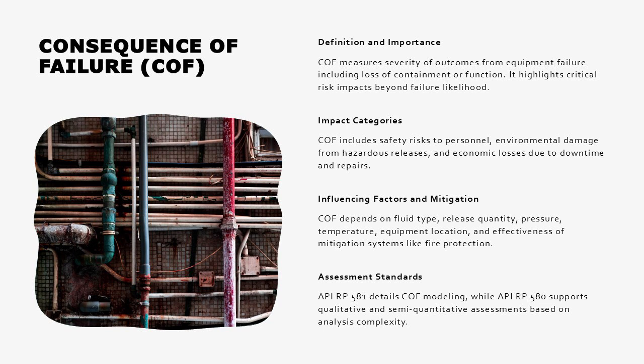COF is influenced by factors such as the type and quantity of fluid released, operating pressure and temperature, inventory, equipment location, and the presence of mitigation systems such as fire protection or isolation valves. API RP 581 provides detailed consequence modeling approaches, while API RP 580 allows for qualitative or semi-quantitative consequence assessment depending on the complexity of the analysis.